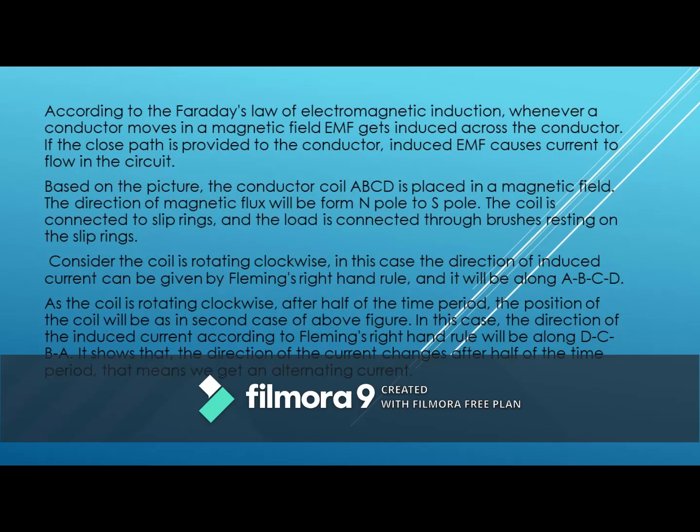Consider the coil is rotating clockwise. In this case, the direction of the induced current can be given by Fleming's right-hand rule, and it will be along ABCD. As the coil rotates clockwise, after half of the time period, the position of the coil will be as in the second case of the above figure. In this case, the direction of the induced current according to Fleming's right-hand rule will be along DCBA. It shows that the direction of the current changes after half of the time period. That means we get an alternating current.